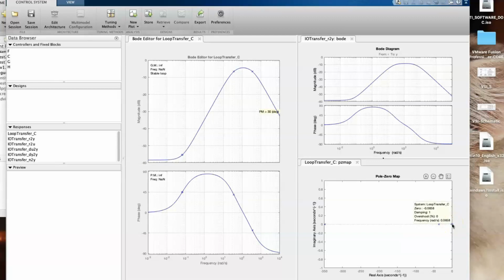These poles and 0 are exactly the same as what we obtained in our previous tutorial using the Simulink blocks to model the closed loop system. If you recall from our previous tutorial, we have set the frequency of the triangular wave to be at 20 kilohertz, and according to our rule, the closed loop bandwidth of the torque has to be a decade lower than this 20 kilohertz, which is 2 kilohertz, equivalent to 12.56 kiloradian per second.